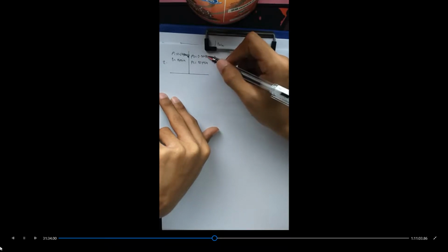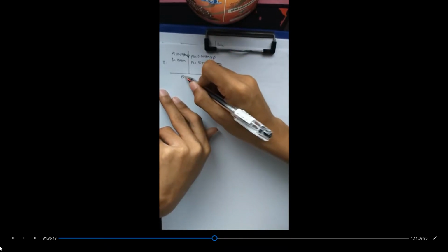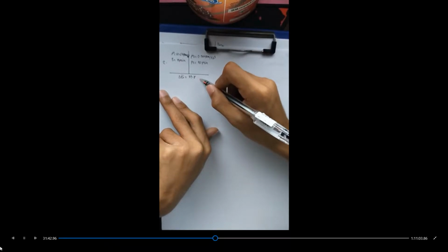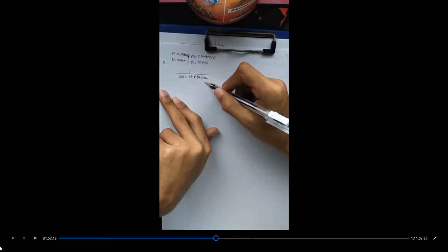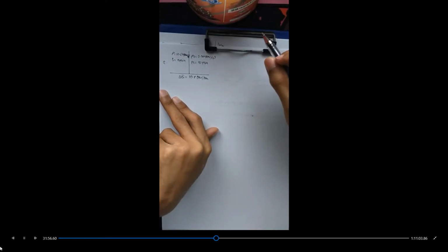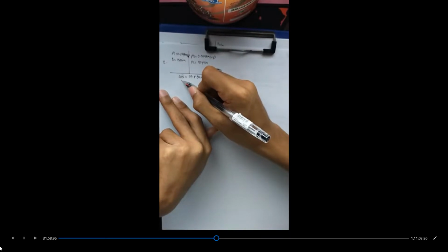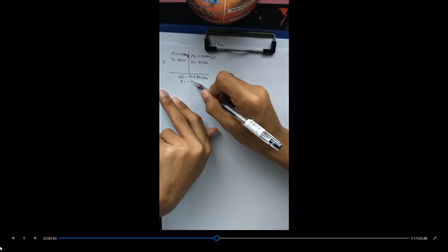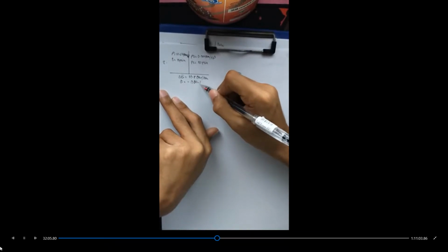and then the change in specific internal energy increases to delta U equivalent to 33.8. It is positive because it increases to a certain value, so that's why the sign convention is positive. And then the heat transferred by cooling, so the keyword here is cooling, therefore the sign of our heat is negative 13 BTU per pound mass.